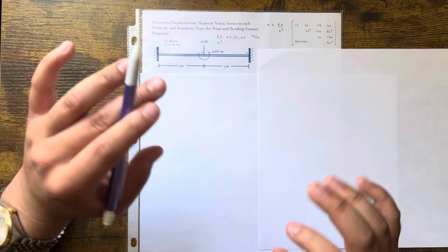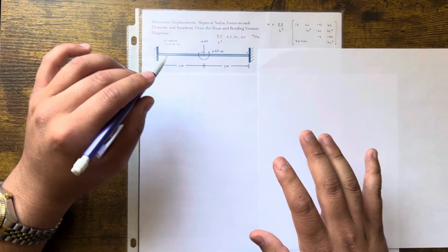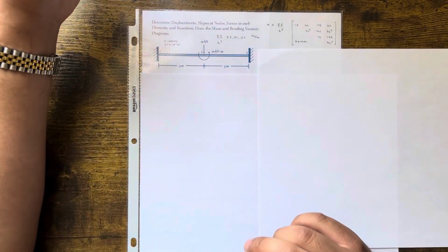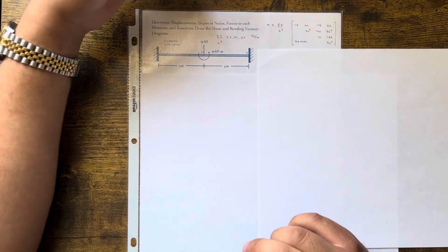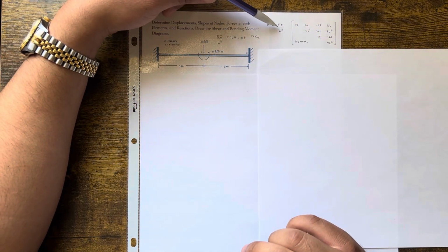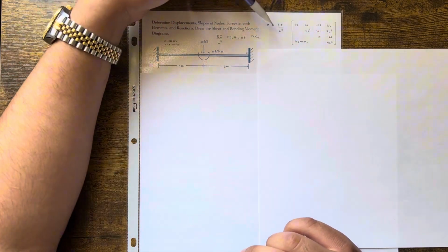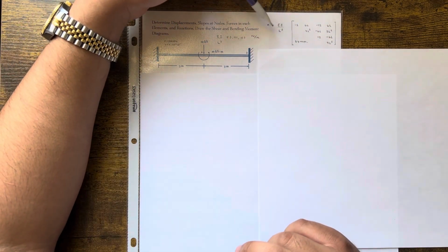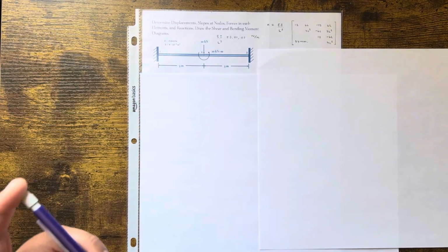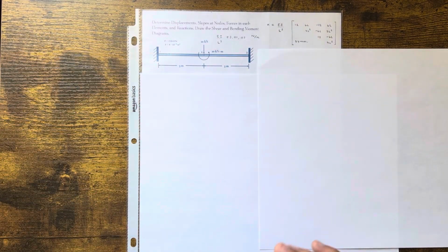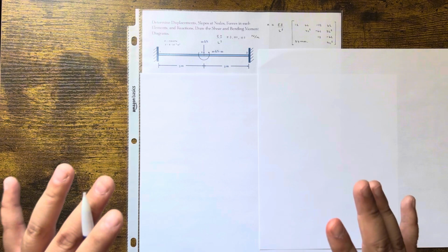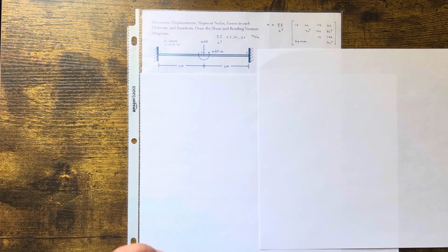So you're able to discretize the system in 2 elements, right? To get the stiffness of each element, you use this right here. K is equal to EI over L cubed. This is just from the book, right? From the chapter. So this is the stiffness matrix that you're going to be using for every single problem in your homework and exams that relate to transversely loaded beams, okay?